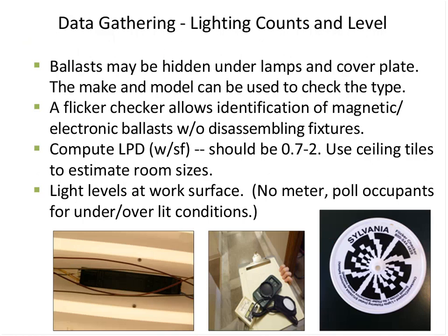So you can question people in there about the lighting conditions. If you have a light meter, we like to go around with a light meter, measure the lighting levels in offices, that type of thing. A typical office should maybe be 40 to 50 foot-candles on a working surface. You can find up to 100 in many places. It's kind of, you could conduct an operation in there. So you need to look at appropriate lighting levels.